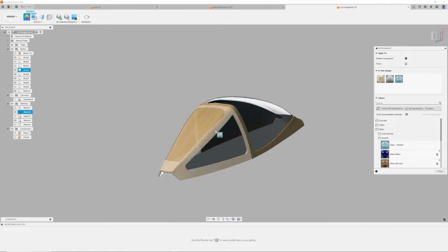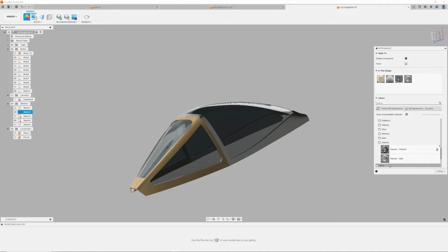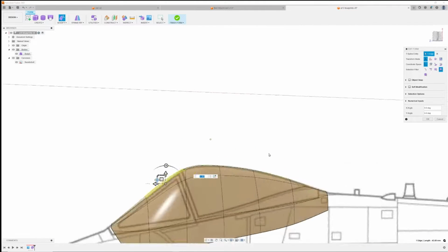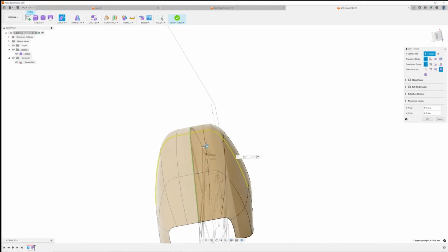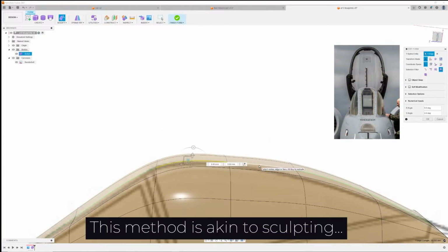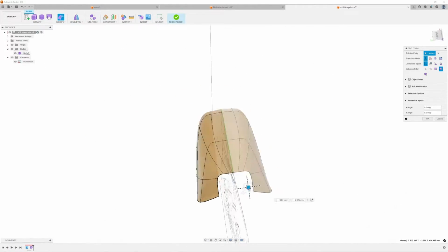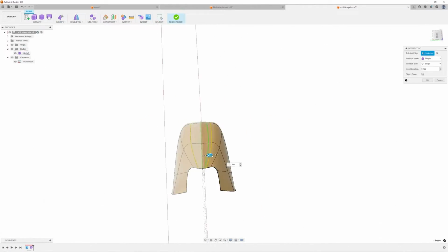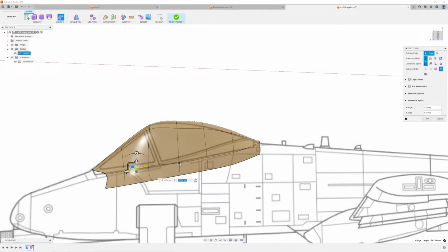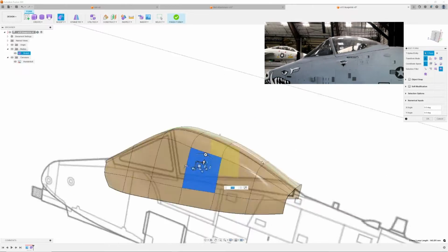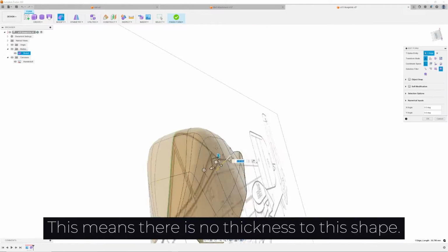Before we start, let me give you a bird's eye view of the process. First, we will work in Fusion's Forms menu by inserting a plane onto our canvas. Next, we will mold the plane to the shape of what we are trying to model. In this case, it is the A10 canopy. The following step will have us using sketched canopy lines to make cuts into the form we previously molded. Finally, we will add material and color in Fusion's render environment. The narration will add information and insight my last video may have missed.